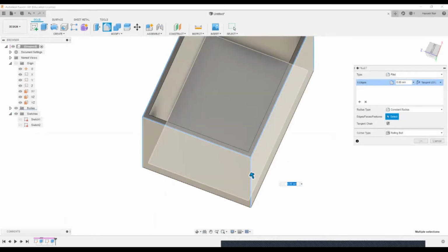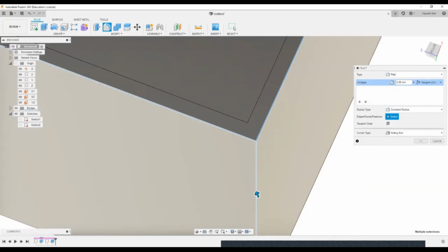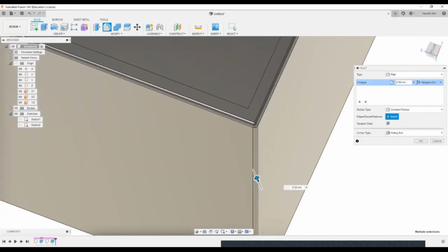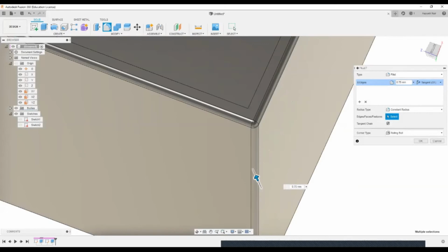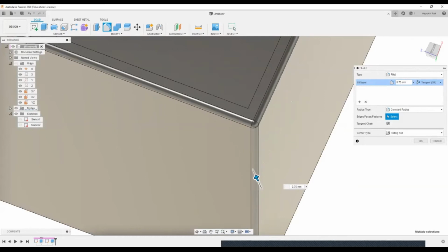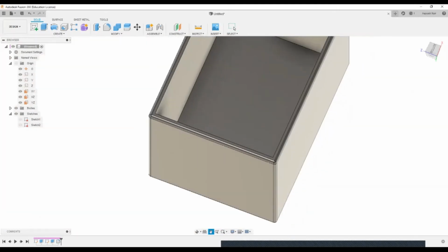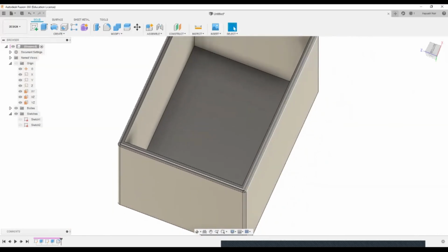Okay, so now I've selected all the sides and you can see what I'll do. I'll add this fillet. You can see what is happening, right? The edges are becoming smoother. Okay, so I'll just add it to around 1.5. Okay, the 1 is enough. Okay, 1 millimeter of radius. I have selected OK. Now you can see it is smooth, right?